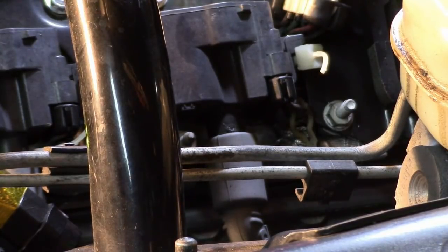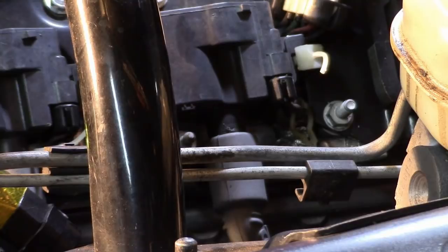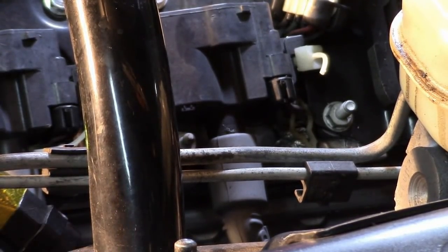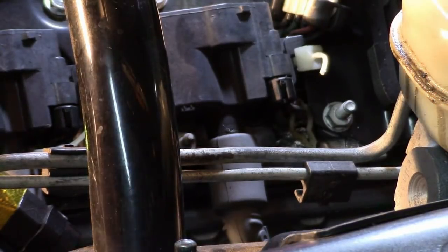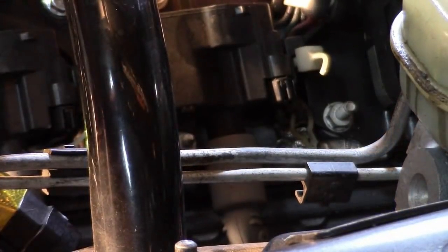The nice thing I like about the coil-near-plug is this allows me to use my scope to do secondary ignition testing by clamping the spark plug wire, something we found, of course, we couldn't do in the last video because of the coil-on-plug design. As you know, we made up for that by just measuring the primary ignition, and we will get into some other things to do when you're in that situation, now that you know the difference between primary and secondary. If you're only able to access primary, that can be a little limiting, and we'll talk about that in future videos. So what I want to do is, we've got a main connector here for all of these.